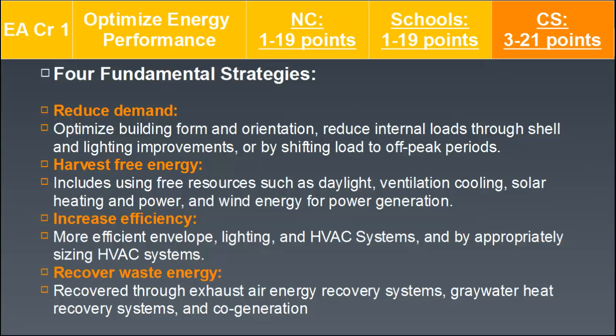HVAC systems, having integrated HVAC systems that maybe correlate to a mixed mode, more passive system. And appropriately sizing your HVAC system, and an energy model can help with that. HVAC systems are typically designed to their maximum level due to code, but if you look holistically at your building envelope with your HVAC system and actual usage of the building, you can usually downsize those systems.